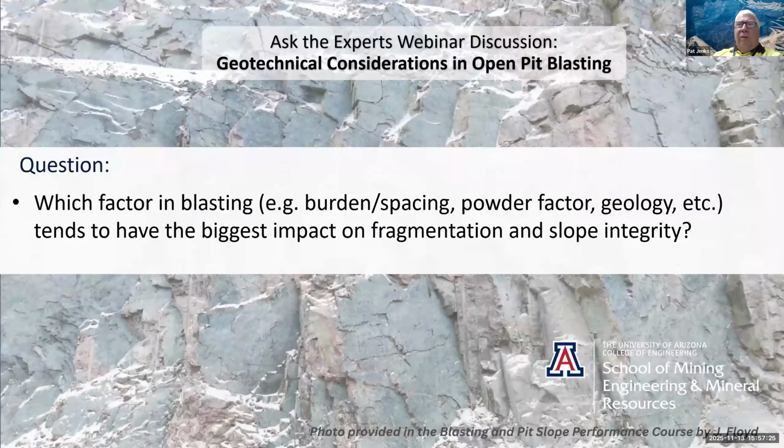And they weren't asking for redrills of those holes. They were just pulling the patterns in, increasing the powder factor, and really, really hitting the rock, the pattern, and the slopes were hard. That resulted in more performance issues with respect to the high wall. So I think that's a key fact that might get overlooked that we definitely need to key in on.